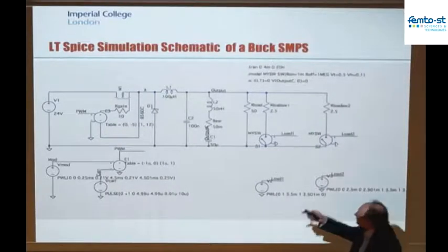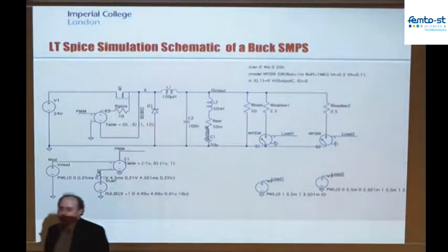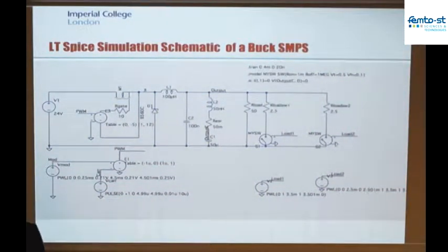And an electrolytic capacitor, unfortunately, is far from being a perfect capacitor. If you put a square wave current into an electrolytic capacitor, you won't see an integration of that into the voltage, because in actual fact, it has reasonably significant self-inductance and probably reasonably significant resistance as well. And so the voltage you see across that capacitor will not be as small as you expect it to be.